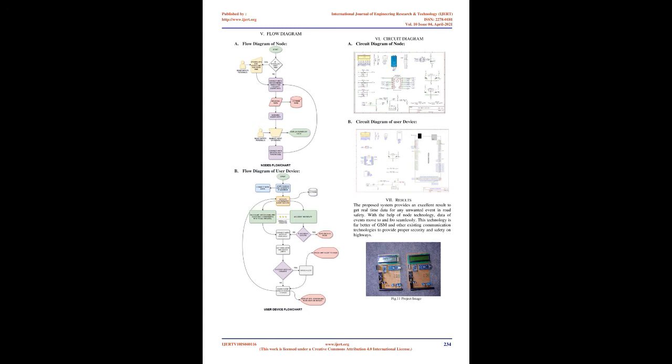LCD modules are very commonly utilized in most embedded projects, the rationale being their cheap price, availability and being programmer-friendly. Most folks would have encountered these displays in our day-to-day life, either at PCOs or calculators. The looks and thus the pinouts have already been visualized above. Now let us get a little technical. 16x2 LCD is known as so because it has 16 columns and 2 rows.